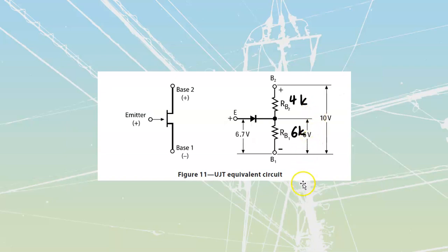These values then are going to have voltage placed across them. And as I place a voltage across it, I am going to rise until I hit a value called my intrinsic standoff ratio, or whatever it needs to be for this thing to fire over. What we do with this is as soon as we exceed this value, here's 6 volts out of 10 volts, 6k out of 10k ohms, plus this actual PN junction, because we've got a P-type material that's embedded inside there, so we're going to have that small amount of depletion region, or barrier potential as it's sometimes called, that we need to overcome.